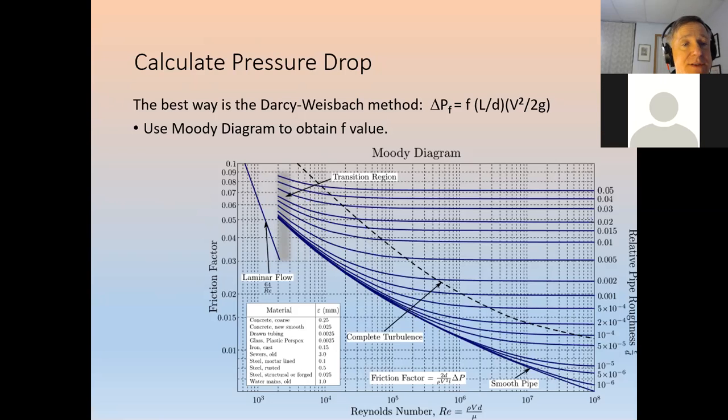And there's a lot of information on this diagram, but what you'll see is the pressure, or the drag, the pressure drop, delta P in this case, is a function of velocity squared. It's also a function of this F value, this friction factor, which you can pull off this Moody diagram. And this Moody diagram is really cool. This is really applied stuff. And I've got an equation on here that can be used instead of this. There's the Colebrook equation and some equations that take this and put it into sort of the form that you can put into a spreadsheet, and you're done for the rest of your life. But so you have velocity squared and friction. Those are the two things I'd like you to note.